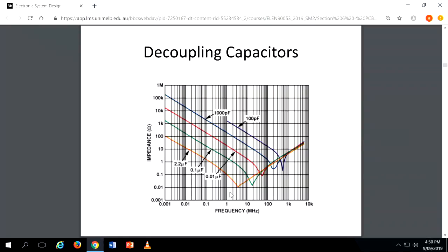You might be wondering what I am talking about, parasitic. So there is a parasitic capacitance, parasitic inductance, parasitic resistance. For example, each capacitor has a parasitic inductance, so the capacitor is not a capacitor at high frequency. For example, the 2.2 microfarad, after 3 megahertz, is an inductor, not a capacitor. So that is called a parasitic. You did not make it as an inductor, but at high frequencies that effect comes into the picture.